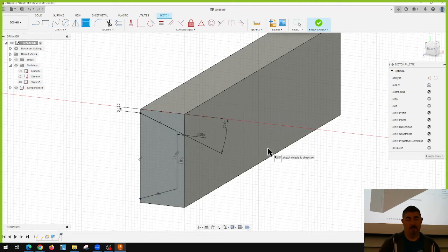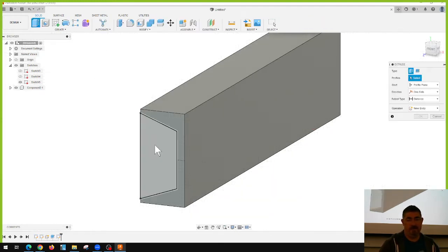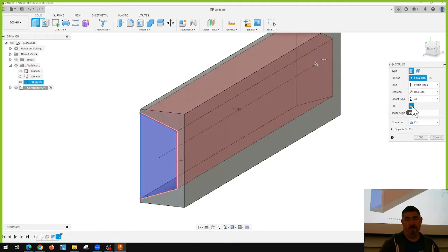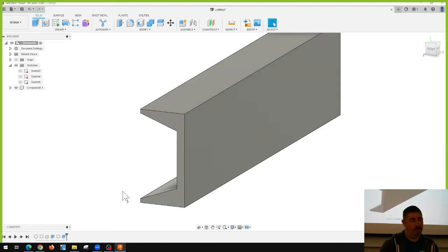Well, copy the same one. Yep, because it's symmetric. Because making those equal, it has to be the same. I don't know if these are right. I don't know if this is right or that's right. I'm just going to do it. Finish sketch, extrude that all the way through, flip the direction. Okay. That way it cuts it out. And I do it all the way through because I know I'm going to make this longer later, so I want to make sure it still cuts through.